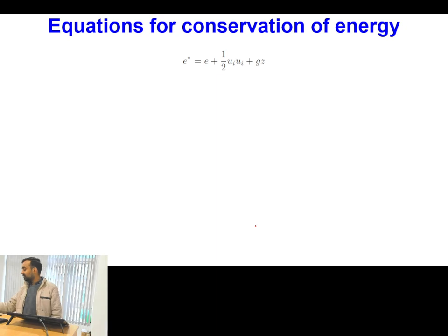Now this is about the momentum relaxation time. After momentum, what else can happen? It can happen that the particle which we are dropping into the surrounding phase is hot or colder in comparison to the surrounding phase. If the particle is hot, of course it will lose heat into the surrounding continuous phase, and if it is cool, then it will gain heat until it comes into equilibrium with the surrounding phase. I have given you one example: in fly ash, particles are conveyed with compressed gas.